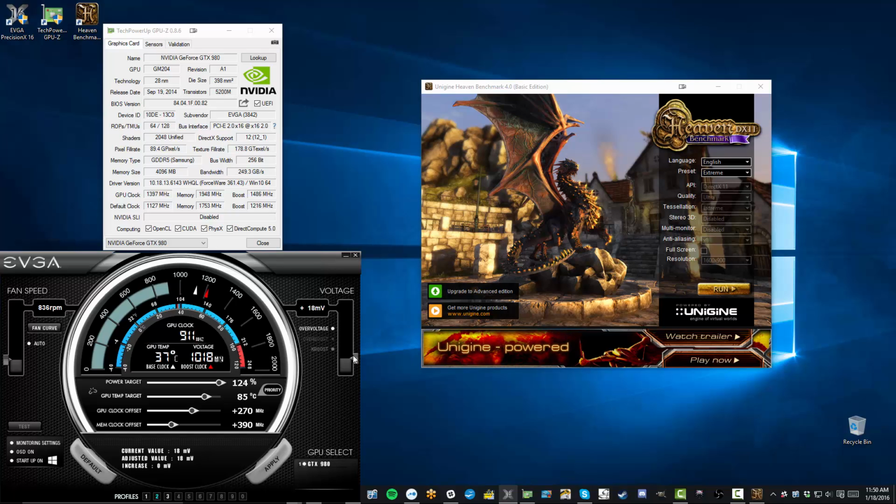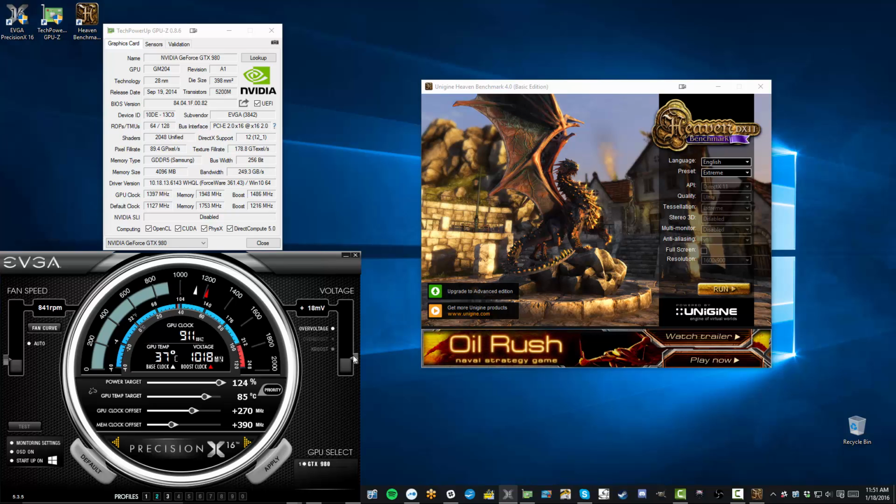This is one of the core differences between MSI Afterburner and EVGA Precision. I noticed in MSI Afterburner I could simply drag the voltage meter anywhere I wanted and overvolt my card any way that I chose. When I switched over to EVGA, I noticed that it had specific increments in those volts, and when I adhered to those increments, I got better stability out of it.